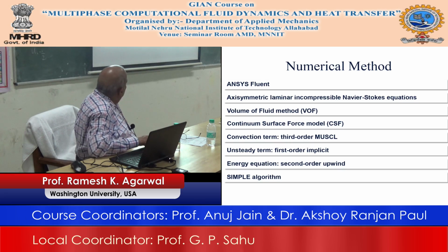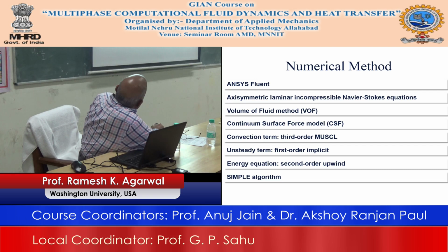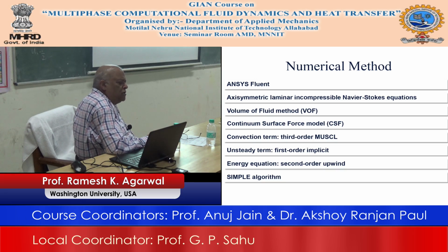Again, you will find that the same theme is coming up in terms of the algorithm that we have used. As in the previous two examples, it is the incompressible laminar volume of fluid method, and in every case we have used the continuous surface model for the surface tension, and third order upwind scheme because it gives better resolution. First order implicit in the time integration, and second order upwind in the solution of the energy equation, which is slightly different from the third order upwind scheme. And the SIMPLE algorithm is used in all the cases because that is the one that we have.